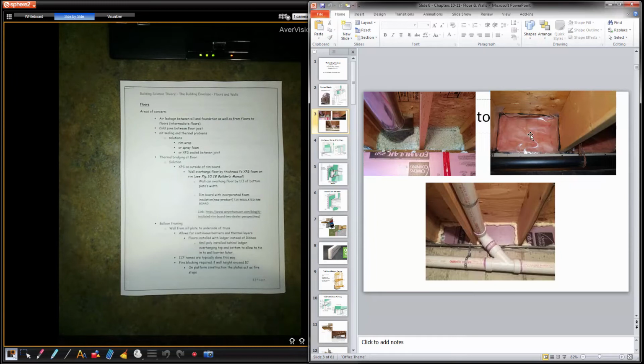That thermal insulation in a basement should be something that can accept moisture to a certain degree. So fiberglass insulation in the floor system is not as bad, but preferably you'd like to see rock wool there. Why? Because there's lots of moisture in the basement in the summer months. So just keep that in mind.